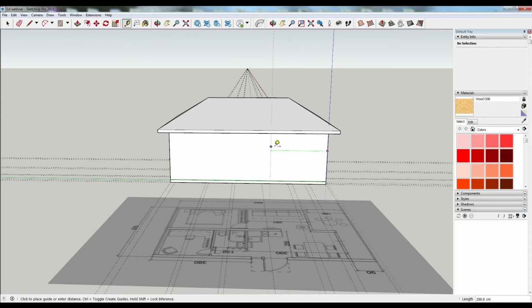I will now use the tape measure tool for the wall so that I could type the size and the line that will be the starting one for the opening. I will click on the rectangle tool, click on the starting point and write down the sizes.